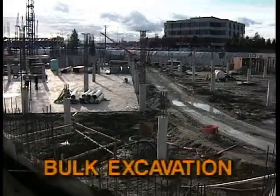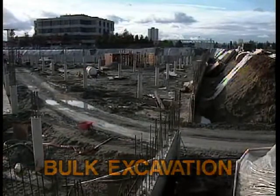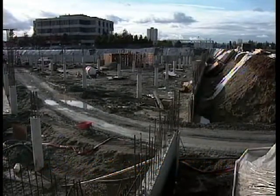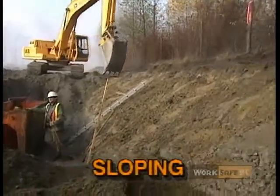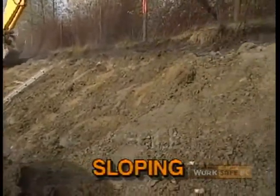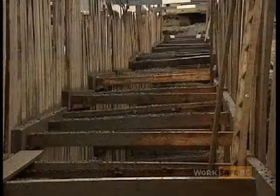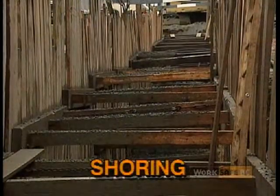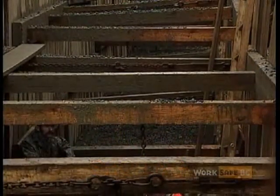A bulk excavation refers to excavations wider than 12 feet, such as basement excavations. Sloping, a system where the sides of an excavation are flared to a safe angle. Shoring, a support system designed to keep the sides of an excavation from caving in.